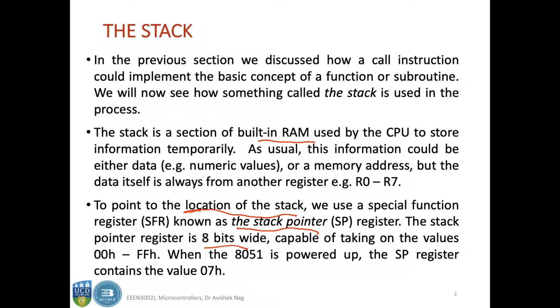And when the 8051 is powered up, the stack pointer register by default contains the value 07. So see, it doesn't start from 00. The stack pointer starts from 07, and if you push some information on the stack, then the stack pointer increments. If you pop some information from the stack, then the stack pointer decrements.